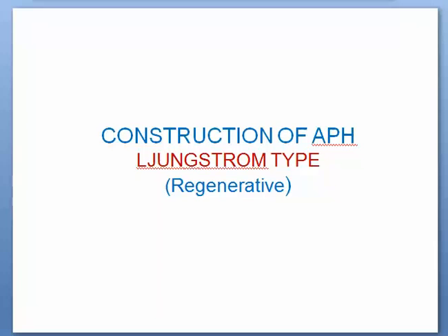After learning why an air preheater is needed in a thermal power plant, its role, how it contributes to increasing the thermal efficiency, and its types, of which there are two, recuperative type and regenerative type, we will now discuss the constructional detail of the air preheater, which is basically the Ljungstrom type regenerative. Our focus will be only on this Ljungstrom type regenerative air preheater.